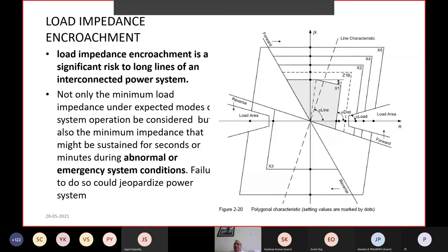Overload condition will normally be a three-phase phenomenon whereas a fault can be single phase to ground or double phase to ground or three phase to ground, and there will always be a zero sequence current flowing if there is a ground fault. Whereas the load current will normally be a three-phase phenomenon, there won't be zero sequence current. And in this region then the protection is blocked. Of course, if a real fault takes place, during fault time, this block will get removed.